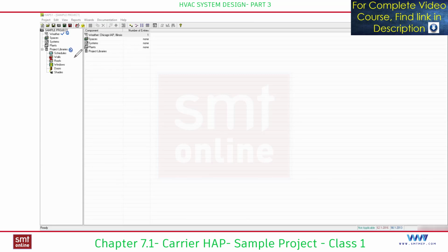Just at this level, try to understand the sequence of operation. After completing the project settings, what we did just now, step one is input weather data as per your location. Step two is updating the project library, like updating the U value for the wall, roof, window, door, etc., including the schedules if applicable. I'll show you this.